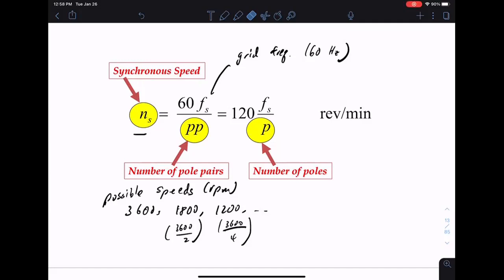If we're just looking at induction machines, it's not possible to achieve arbitrary speed. There's not that many speeds to pick from. So if any of you goes on to take machines and drives as a capstone, or has taken that, or is taking that right now, you see how to make more advanced drives. Any questions about the poles and machines? Okay, so this is our calculation of synchronous speed. For almost every question, you need to figure out what the synchronous speed is. So this is definitely a useful equation to remember.